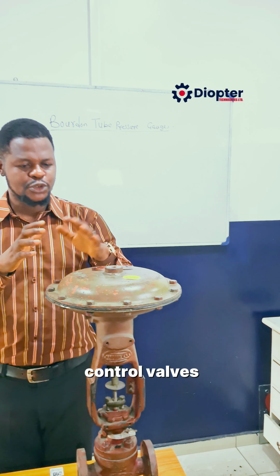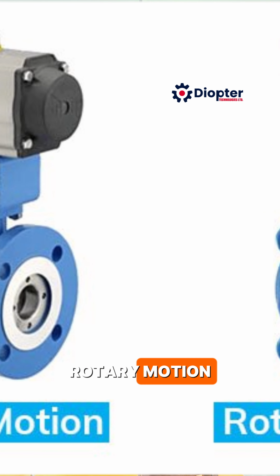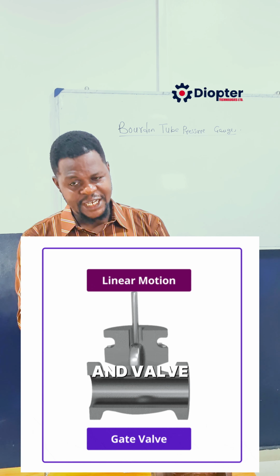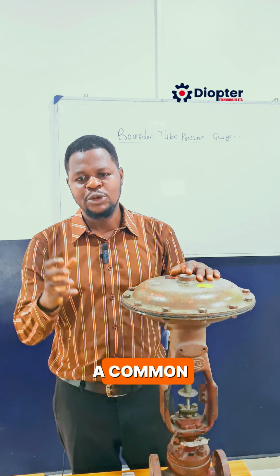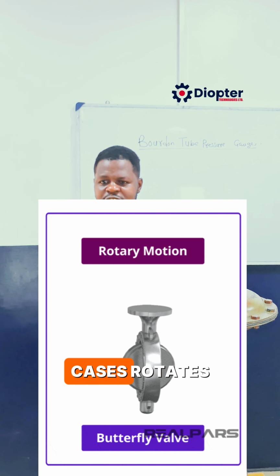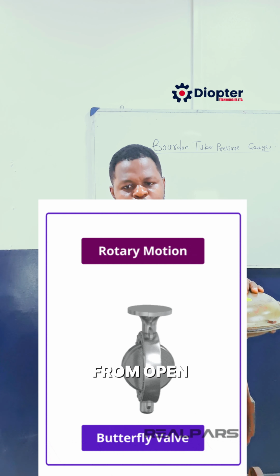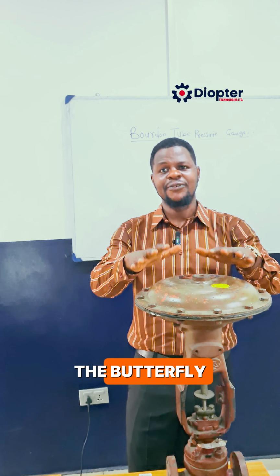The two classes of control valves are linear motion and rotary motion types of control valve. On a linear motion valve, the stem and valve movement is up and down. A common type of sliding control valve is the gate valve. A rotary motion valve, in most cases, rotates 90 degrees from open to the closed position. A commonly used rotary valve is the butterfly valve.